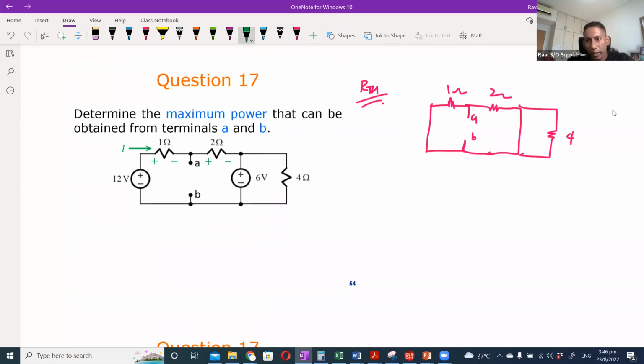All right. So again, if I were to imagine that I put a supply here, when the current flows out over here, from this point, it will split to here and here. So it split to 1 and 2. When it passes through 2 at this point, it sees that you have a 4 ohm branch and a short circuit branch. And as I mentioned earlier, it will always take the path of least resistance. So if there's a short circuit, you automatically go to the short circuit, which means that the 4 ohm is no longer part of the circuit in this situation.